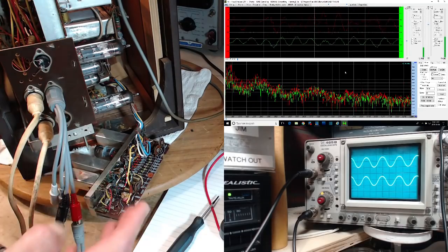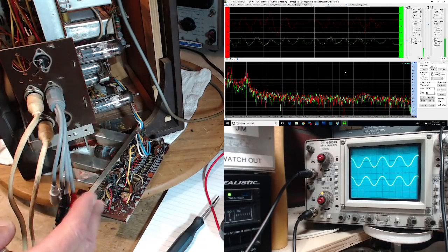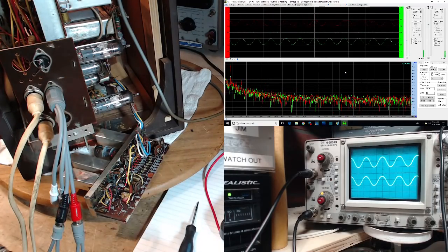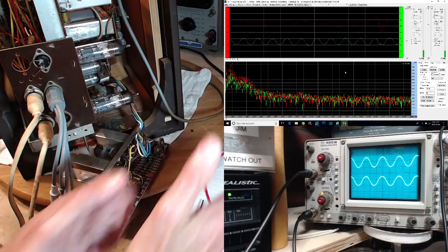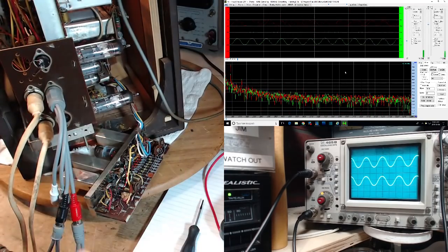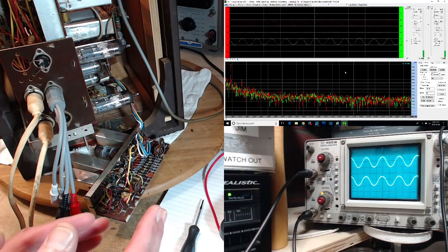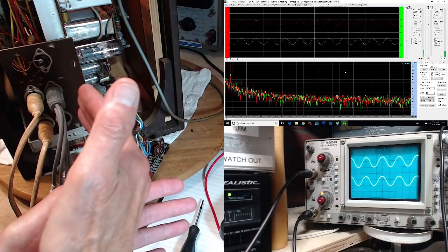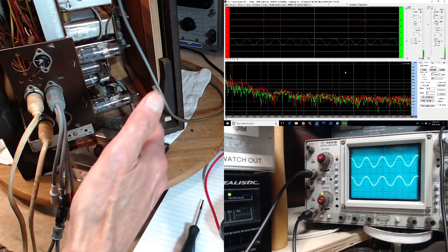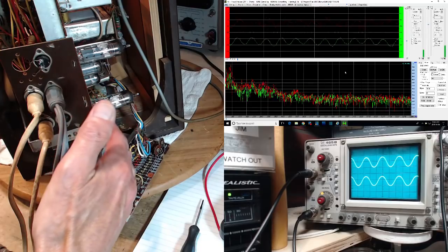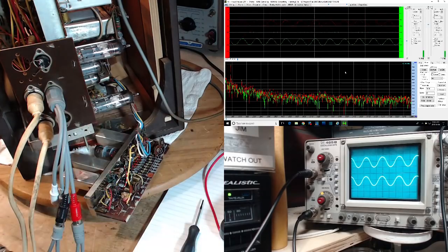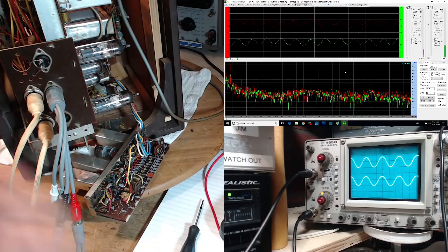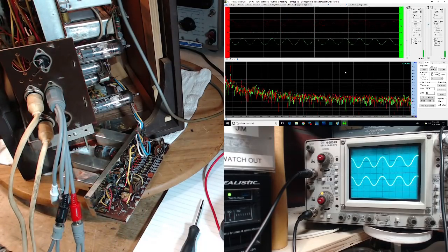And then the 38 kilohertz is used to switch in amongst these diodes that basically switch left, right, left, right. That's basically what it's doing. So the incoming signal is being chopped into left and right, and then directed to the appropriate speaker or appropriate channel of audio. That's what's going on. It's happening so fast you can't hear it because it's based on 38 kilohertz. You're not going to hear that.